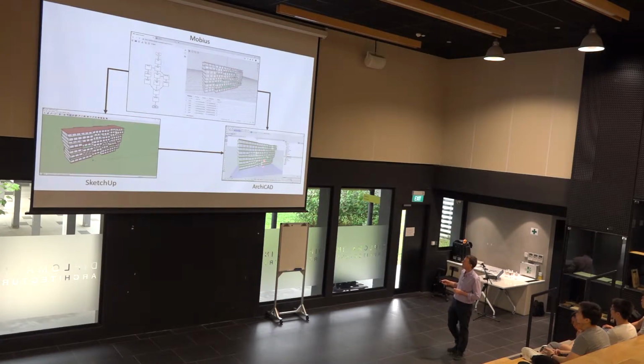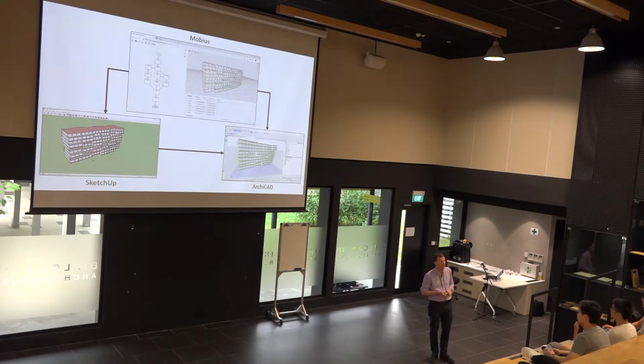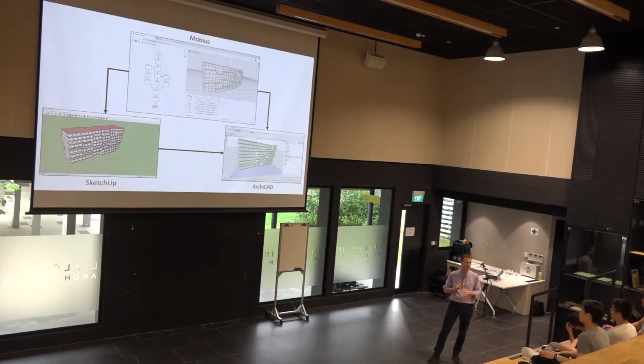When you are importing into ArchiCAD, you're importing a Collada file. Collada is one of the 3D file formats. Then when it comes into ArchiCAD, it's not a BIM model, it's actually a geometry model. And you need to somehow convert it into BIM. Some of those processes are tricky, and I'll give you an example of one that we're still on our to-do list, where we have some slabs, and when ArchiCAD imports them, they don't become solid, they stay as kind of shells. So there are kind of issues.